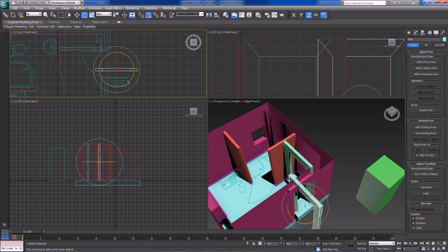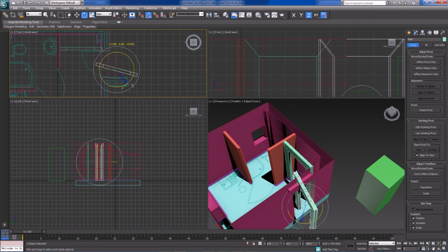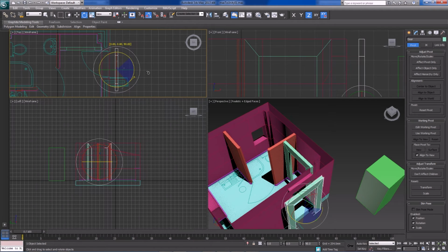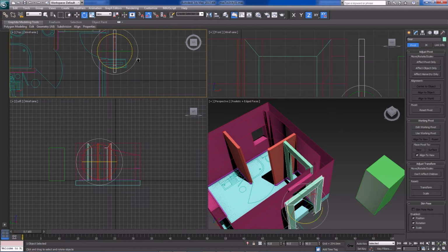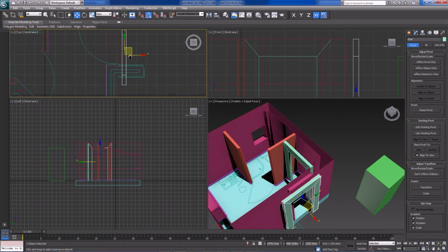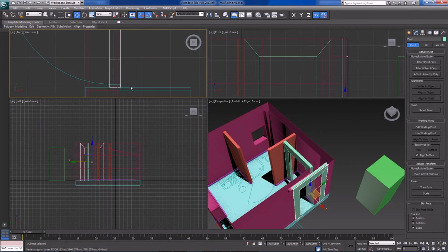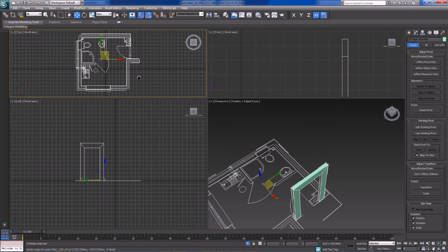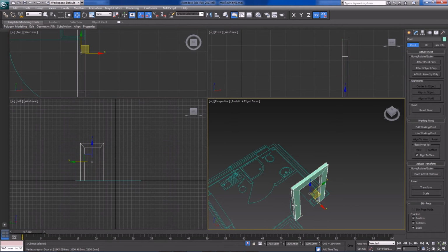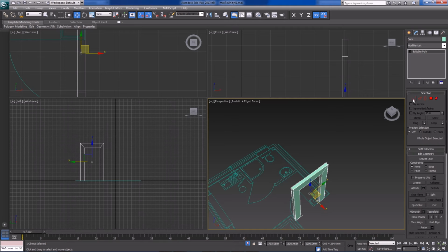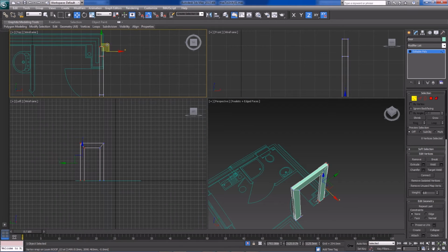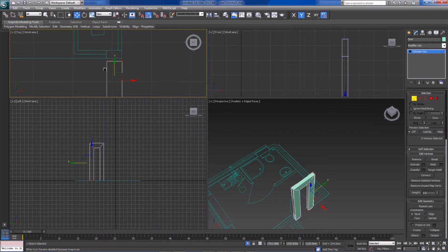Angle Snap tool basically allows us to rotate objects while snapping to angle values. So it's not going to be 86.73, it's going to be 85, 90, etc. So that's what we need to go for, 90 easily. Let's just use one reference point, so we'll snap this to here. And let's just isolate these two objects. This is already an Editable Poly, just worked on it. So now let's just start dragging these vertices in place with S selected. Here we go.